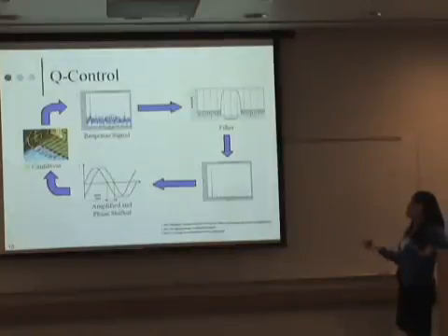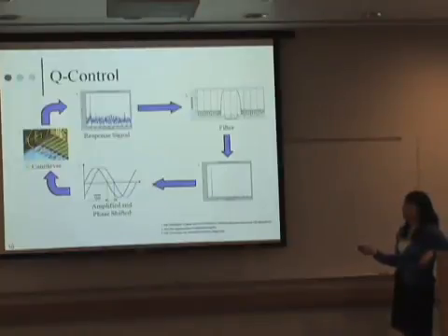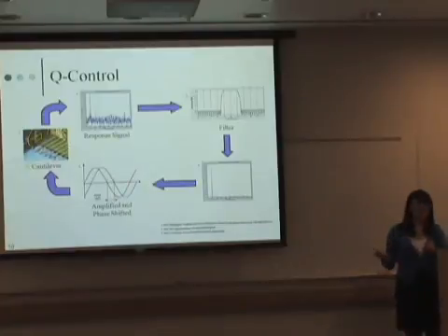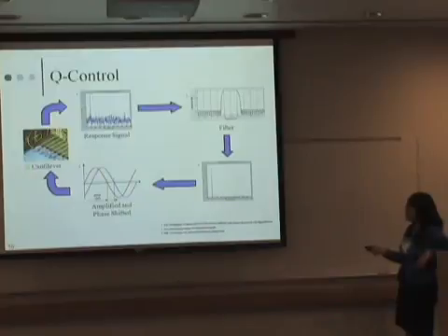So once that is done, you amplify your results, and then you phase shift. So your input and output curves could look something like this. They won't line up on top of each other. And so you want to correct for that, so you have to phase shift it. But once that is done, you use the frequency which you found for this natural frequency, and you input it back into the cantilever, and you use that to actuate it. And so this cycle is repeated over and over, and we did it 10 times.